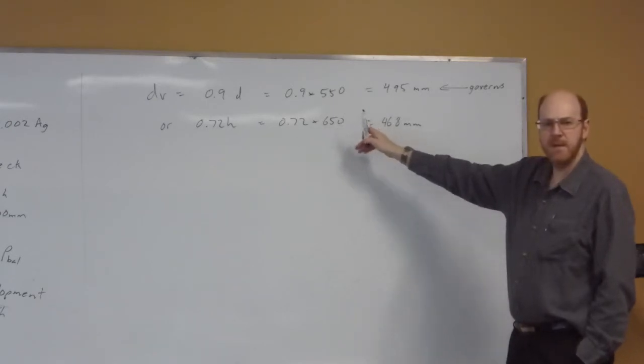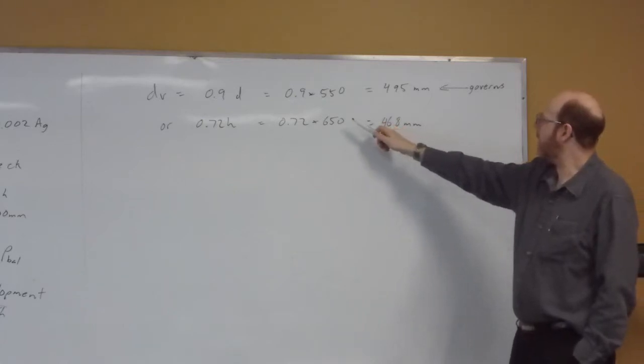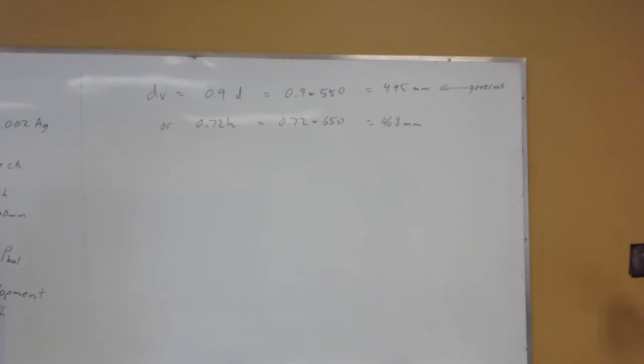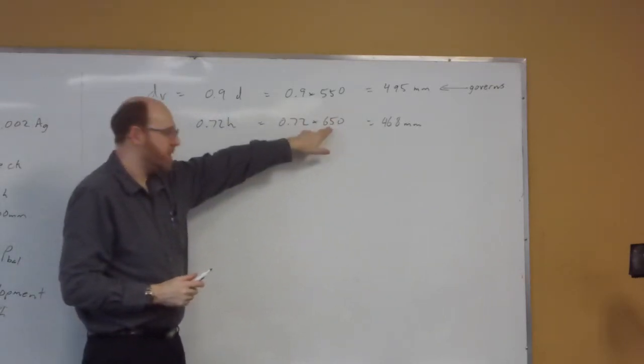Yeah, so what we've got here, 0.54, and now we've gone to 0.55. We've increased the value because we increased the thickness of the footing. Okay, so we had a calculated value of the minimum d that we need. From that, we added a bar and cover distance, and then we rounded up. As soon as I round up, to recalculate d we take our new H and subtract our cover distance and our bar diameter. So this value right here is 100 less than that.